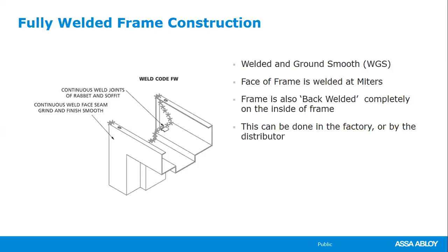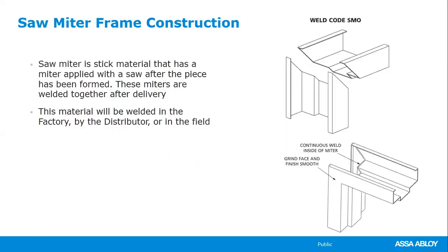Again, you'll see that sometimes specified in hospitals, a lot of times where there's a lot of water, whether it's clean rooms, where they're going to hose down that room every night, or sanitary reasons like food processing plants, chemical areas. You may see the spec calling for a fully back welded or continuously back welded frame. The cost is more than your standard face weld, so I point that out because there's quite a bit of a difference in the price.